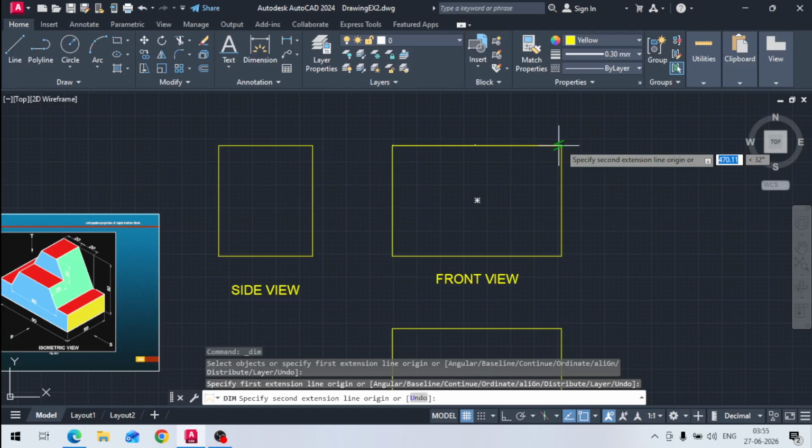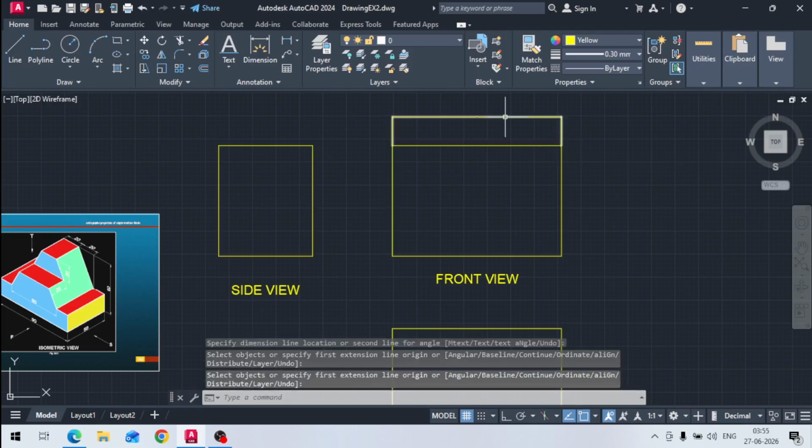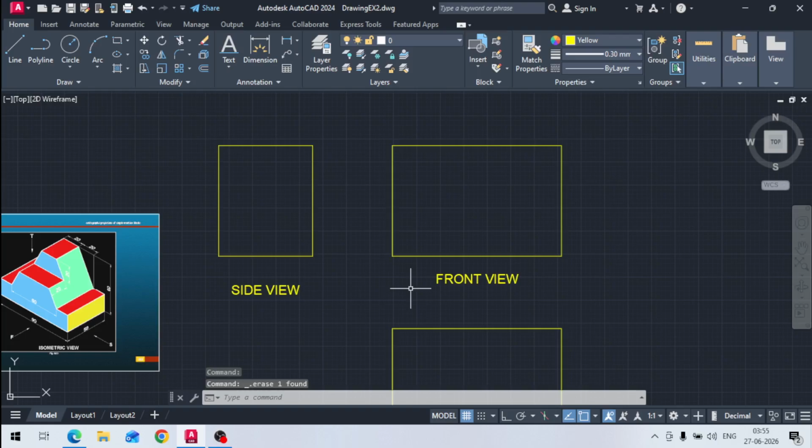Here the dimensions are not visible, so I have to scale the dimension. How to do that? There is a command DIMSCALE. Dim scale 1, I can write here say 8, enter. Now the dimensions will be 8 times bigger in scale. So again I will dimension it now.